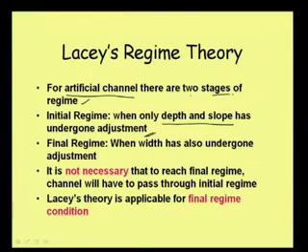Then, after some time, it will start eroding from the side, and its width will start increasing, or it may decrease if deposition starts, meaning the width will start adjusting. When all three parameters, that is depth, slope and width, finally get adjusted, this is called the final regime condition.